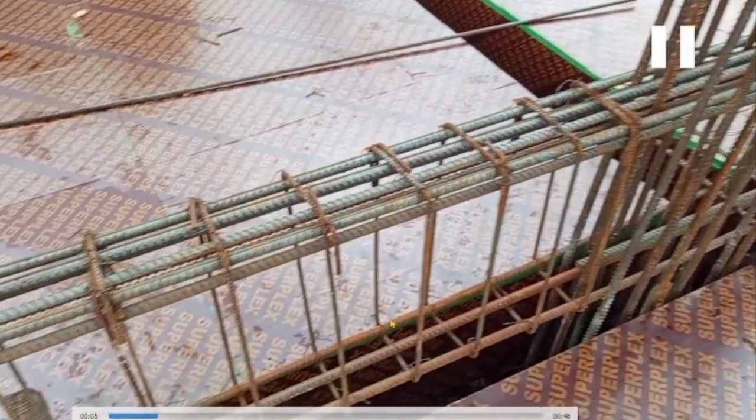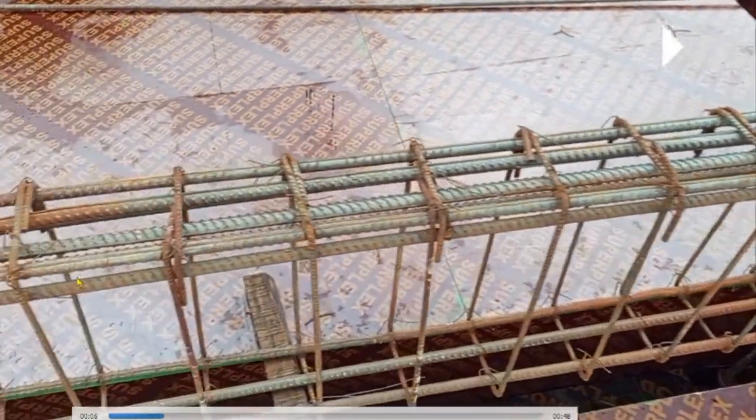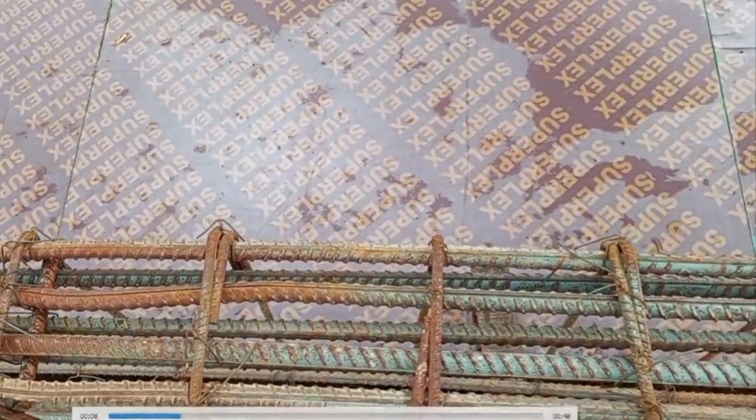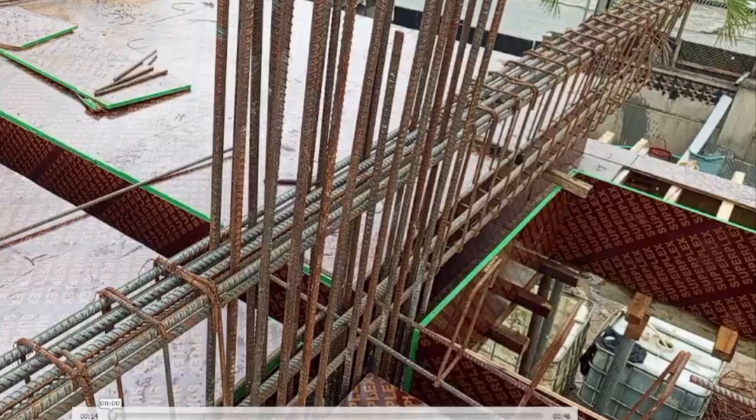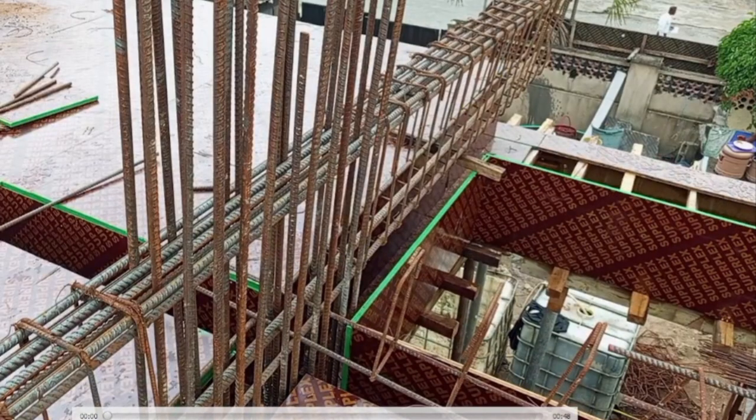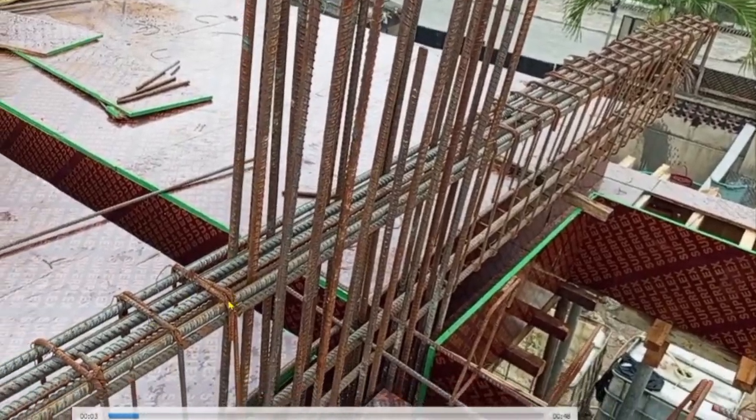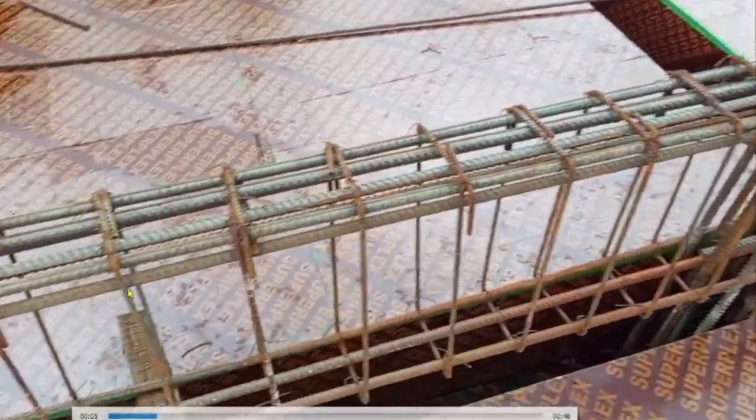You can see you have 3 and you have 1 on top of it. The 1 is going to stop because it does not continue, but this one continues. You can see the first one stops at 1.4 meters from the first support and the second one continues. You can see, okay, it stopped here. I see, then the second one continues. Now let's go back so we can count the number of stirrups. You check this, we should be having 31 stirrups here as well.